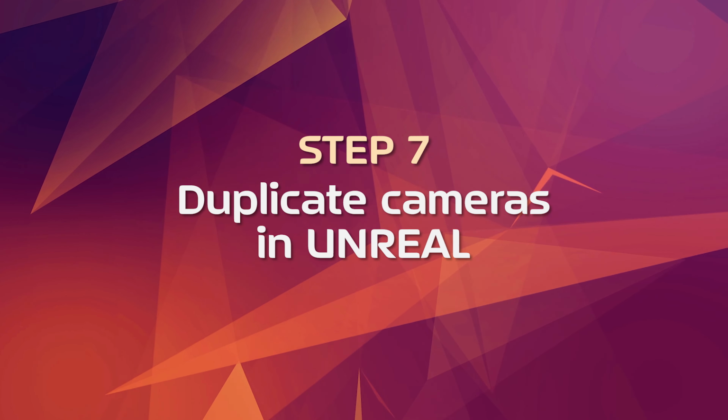In the World Outliner, click on UECam01. At the top of the Details tab, click on the LiveLink component controller object. And then underneath there, find the subject representation and change the drop-down to Maya Cam 01. In the World Outliner, click on UE5.0.2.